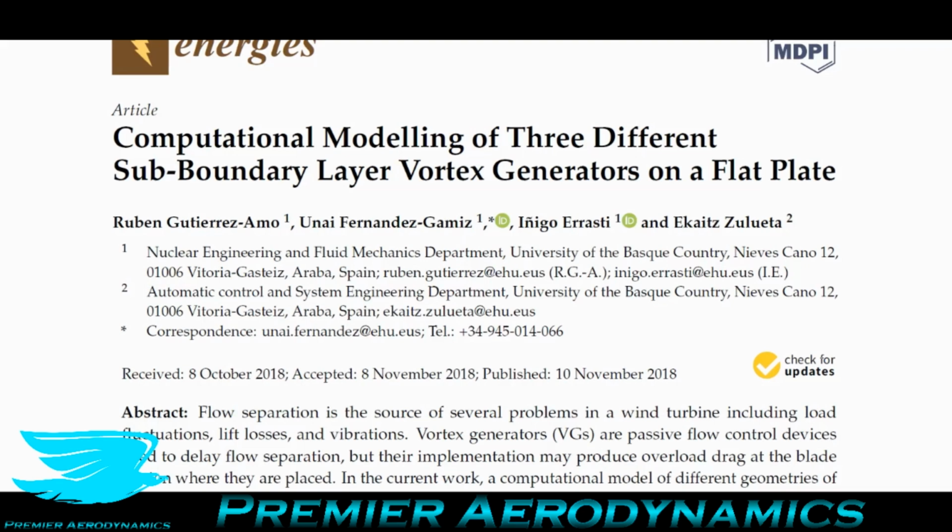So let's make these vortex generators interact with the fluid up there and drag it down. But then they found that there are some benefits to that. So obviously they are very effective in doing that. One problem, though, is that they create a lot more drag. So they create drag not only due to friction, as we'll cover shortly, but also due to an increase in pressure drag, because you now have a lot more vorticity and a lot more wake and chaotic motion.